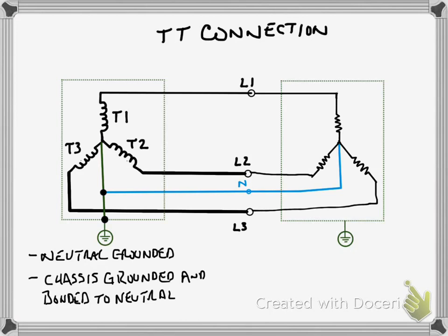And it goes out to the load. The difference is that at the load side, we do not bond the neutral to earth at all, but we do bond the local chassis or provide a local ground. So one of the issues with a system like this is that you can get significant voltages appearing between the neutral point and chassis ground. In most homes and at the point of use in factories and so on, you're not normally expecting to see any voltage between neutral and ground, or at least not very much, a couple of volts maybe.